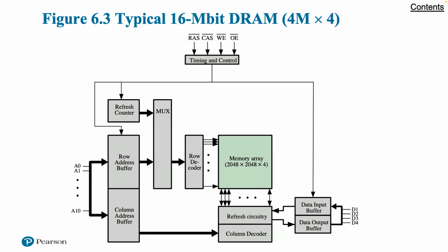As an aside, multiplex addressing plus the use of square arrays result in a quadrupling of the memory size with each new generation of memory chips. One more pin devoted to addressing doubles the number of rows and columns, and so the size of the memory chip grows by a factor of 4.